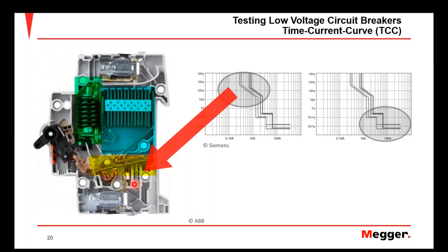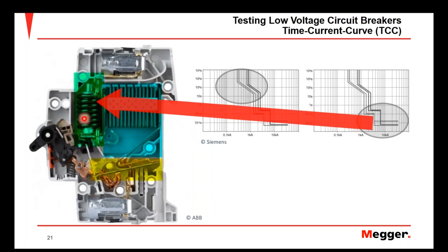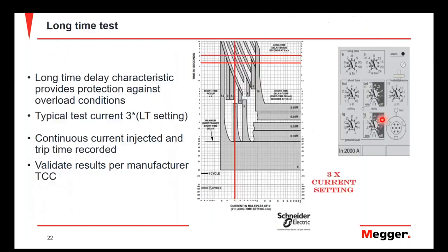And we saw earlier that the thermal protective function works off of a heating effect that occurs in the breaker whenever you have a certain amount of current that flows through the breaker. Additionally, this is the physical representation of the magnetic mechanism that we talked about earlier, that is in reference to the instantaneous function of the time current curve.